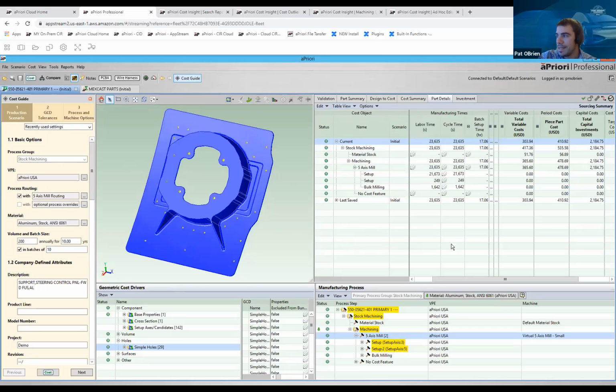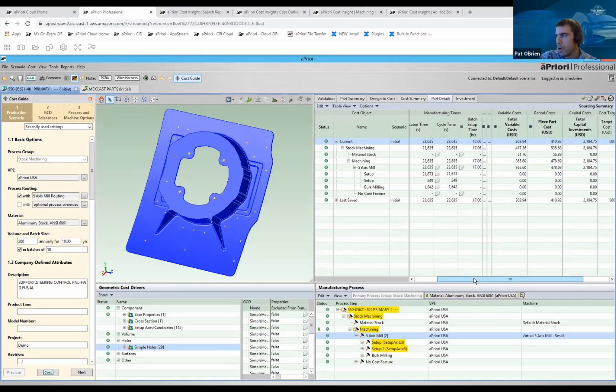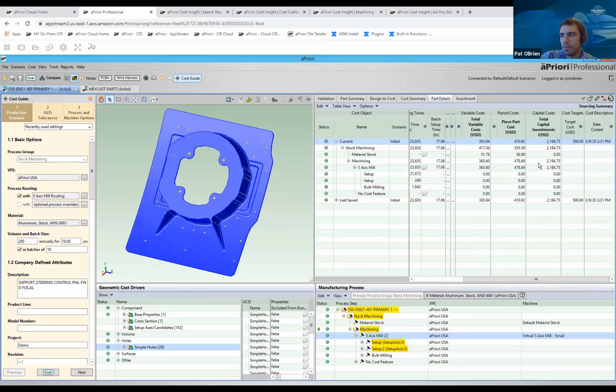We have very detailed manufacturing and routing information for this part, cycle time info, a detailed cost breakdown relative to this part, inclusive of that manufacturing process routing. All of the individual steps, whether or not there's any secondary operations happening along the way. And then finally, all the way down to that individual feature set: the overall length, width, height of the part, the material, how many holes are found in this part, all of those challenging or just standard type feature sets found within a particular component.